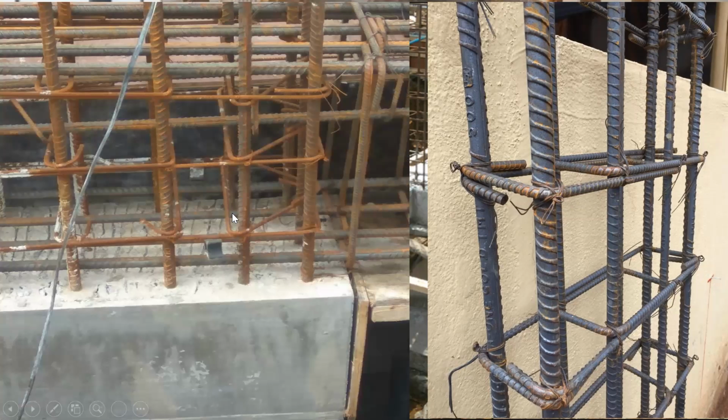So as we saw in the previous slides, this is a triangular stirrup that was provided, right? I mean lateral ties. See, this is connected here, this is connected here, and one more is connected here. So this is how the connection is done. And these are the hooks, that is the links, right? We call it links. So this is how it is bent. You have to bend it at 180 degrees.